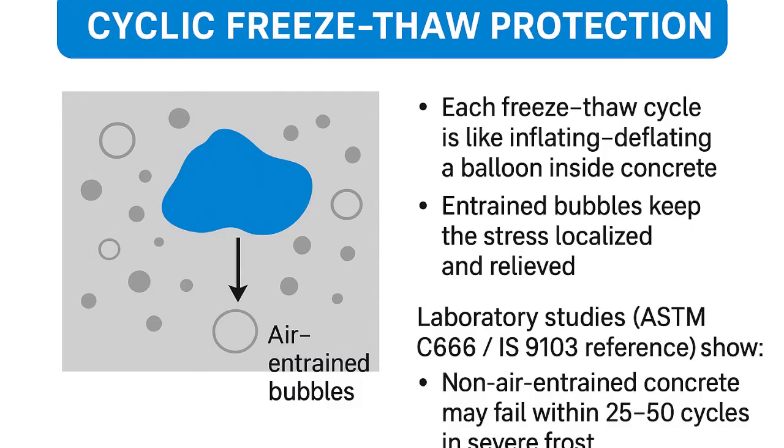So, what do laboratory studies say? That air-entrained concrete can withstand hundreds of cycles with minimal damage, but non-air-entrained concrete may fail within 20 to 50 cycles in severe frost.